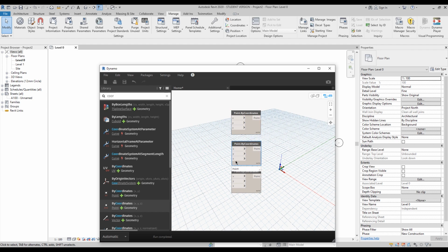This dot will change in the Y direction, so we need a code block, let's say 10, and let's connect 10 to the Y. And here is the second dot, and that dot will get also the Y, but not actually. We need a code block like x divided by 2, and this one will be the Y direction, so it will always be on the middle side.